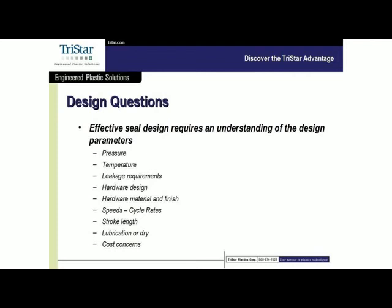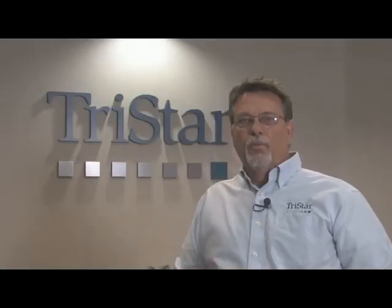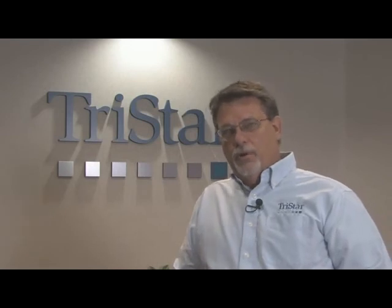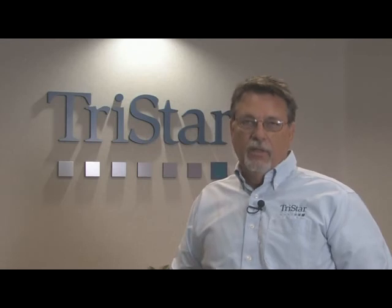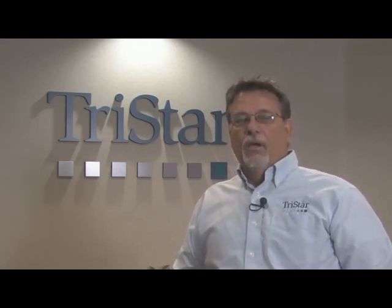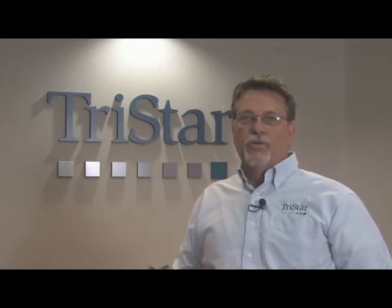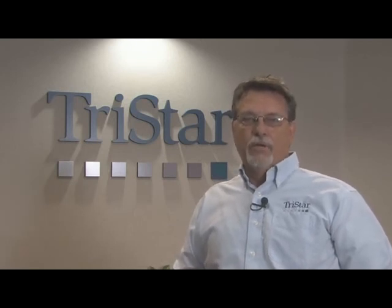And then finally, as with our bearing design program, we also like to know what your cost concerns are. Obviously, if you're looking to replace a rubber O-ring that costs you 20 cents and you want to try and solve your problem for 25 cents using a Teflon seal, I can pretty much tell you up front that that's not going to happen. So, tell us up front exactly what your cost considerations are, because it may be that PTFE seals are not the right direction for you.